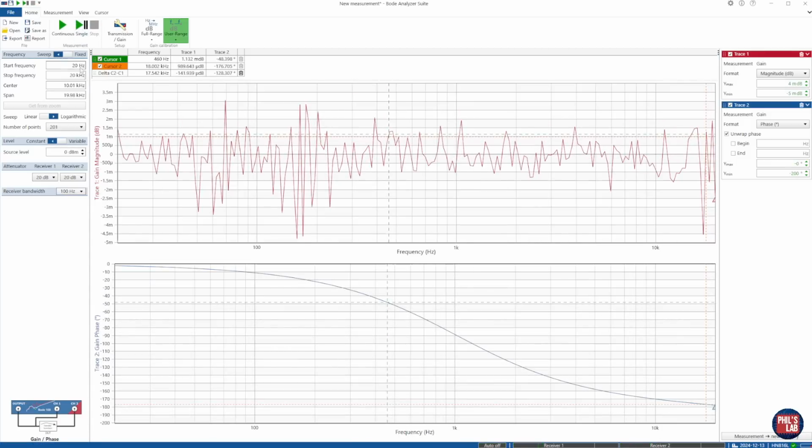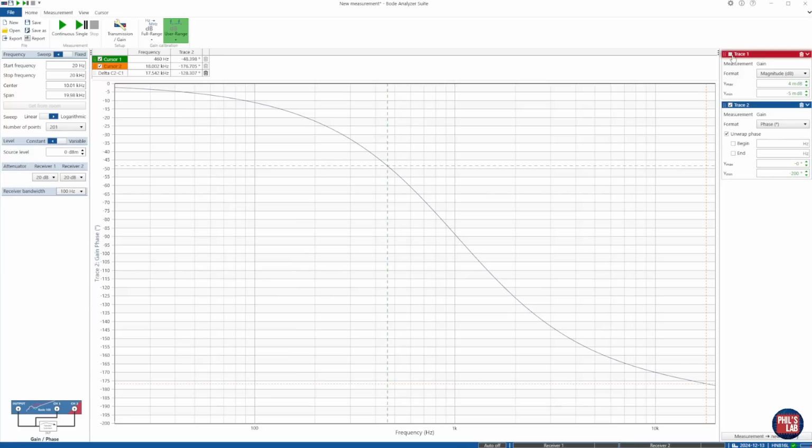And this is our measurement. Keep in mind, again, the magnitude is pretty much flat, although we see these excursions, but again, look on the left-hand scale, we're pretty much centered on 0 dB with only about 3 milli-dB excursions, so this is pretty much flat. So the magnitude is 0 dB flat, exactly what we expected from our filter. So let me hide the gain window, and now let's look at the phase, because that's what is important, as we saw for the all-pass filter. Now I'm sweeping from 20 Hz to 20 kHz, effectively the system bandwidth, but of course the all-pass filter starts at 0 Hz, so effectively DC.